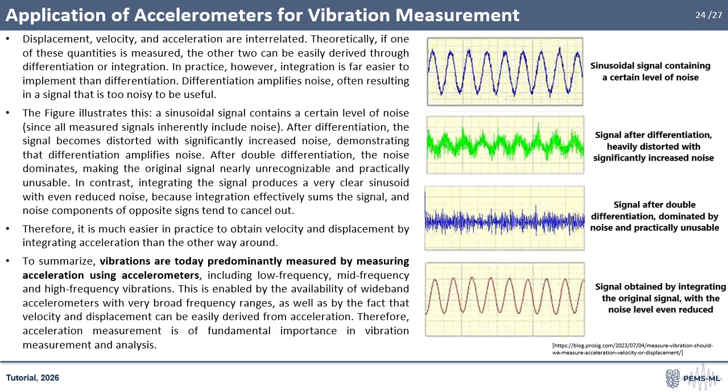Displacement, velocity, and acceleration are interrelated. In theory, knowing one allows us to derive the other two through differentiation or integration. In practice, integration is much easier because differentiation amplifies noise.